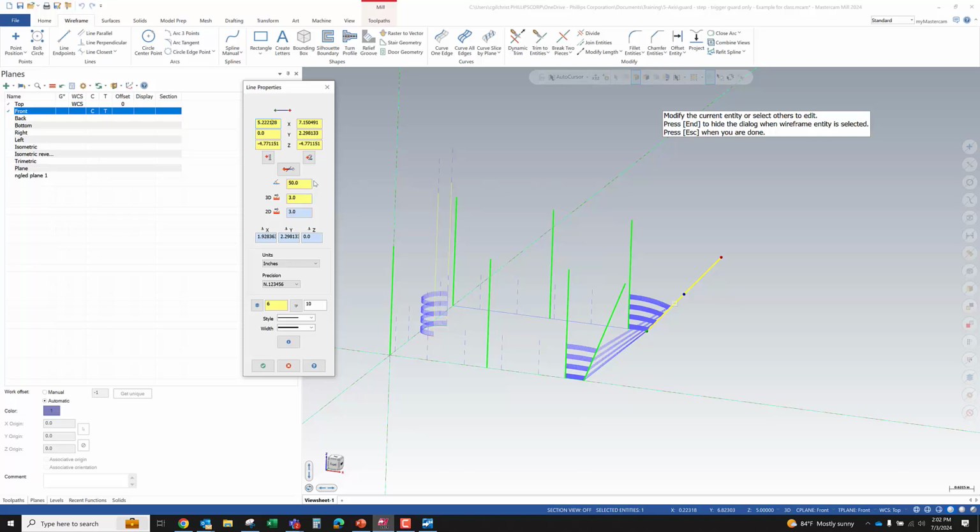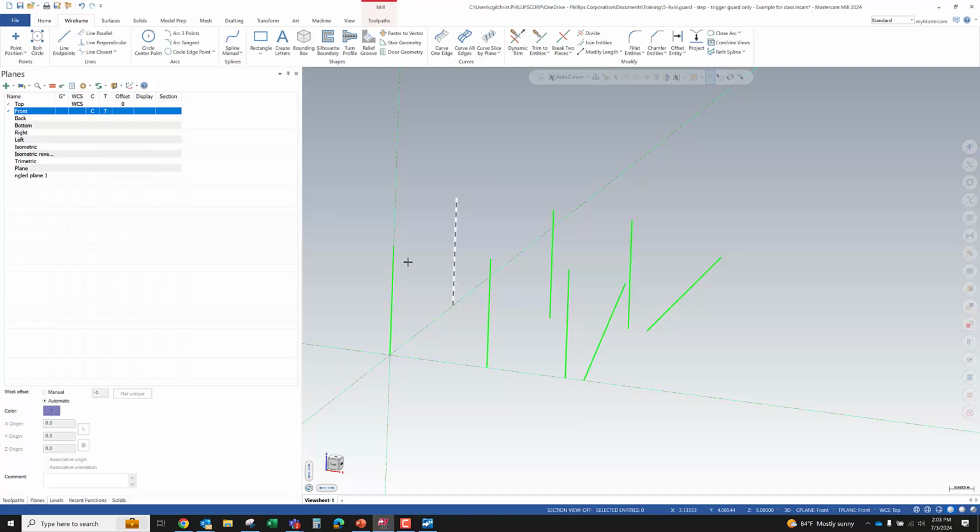When is an arc not at 0, 0 in X and Y? When it's really at 0.000021 in X, when it's at 0.000034 in Y, right? You can have these remainders of millionths of an inch that will affect things like arc breaking, tangency, whether or not endpoints line up. So just something to be aware of there. I would highly encourage you to increase the measurement precision.